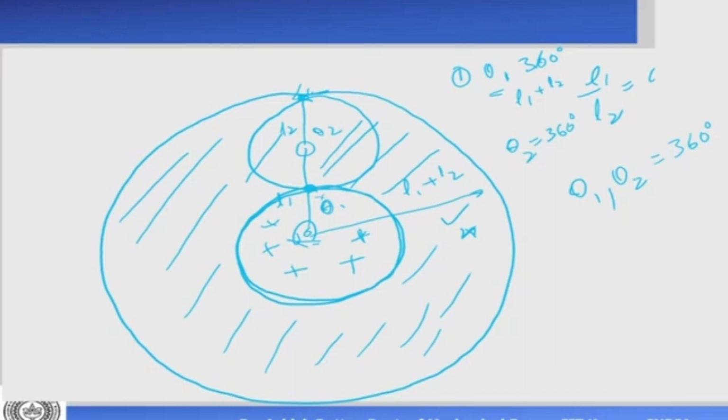So the question that we are trying to answer is what should be L1 by L2? We can say that L1 and L2 should be such that the work area should be maximum. If the work area is maximum, then the end effector can go anywhere inside the work area, and it'll be a good design, right? Now if you look at this figure, when would the work area be maximum? What is the work area? If this is my V1, this is my V2, then the work area is V1 minus V2.